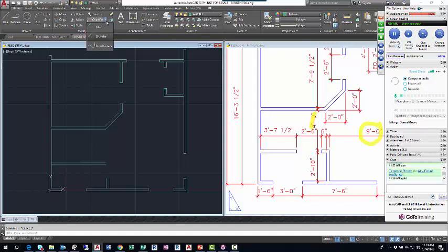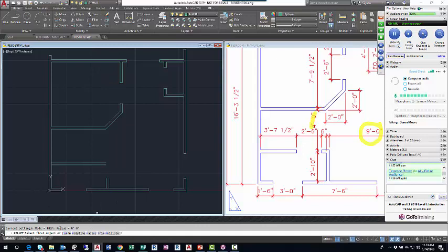I'm going to use the drop down and get fillet started. Left click fillet. The command prompt says the current radius for fillet is 0 feet 0 inches. Well, that corner is a 0 feet 0 inch radius fillet. So I'll left click the right vertical, the top horizontal, just pull those two lines together, basically made them touch. Command's over, I restart it, fillet, left click the left vertical, the next horizontal, just brought those two lines together.